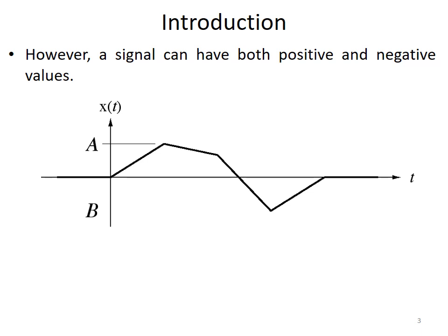However, computing the area under the curve of a signal may give you a wrong result, because some signals, like a sinusoidal waveform or the one that is shown in this figure, have positive and negative parts. So when you compute the area under part A of the signal, you will get a positive area, and when you compute the area under the curve of part B of the signal, you get a negative area. And when you sum both of these together, you will get a smaller area, which won't represent the strength of this signal.